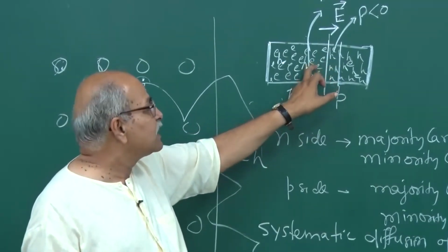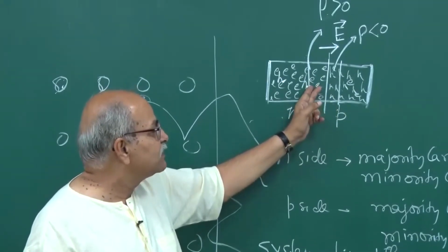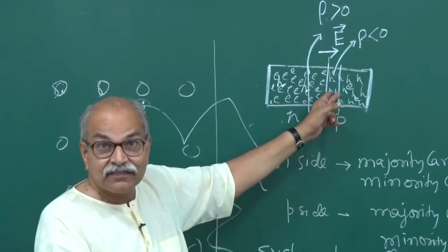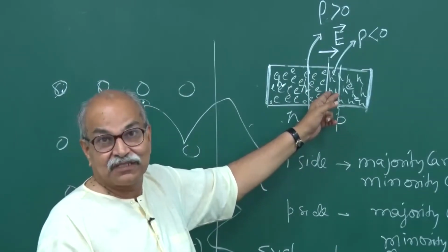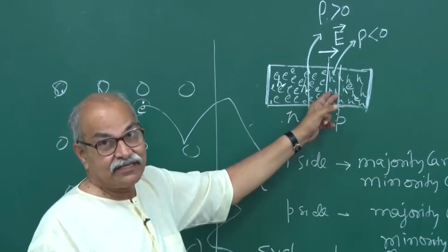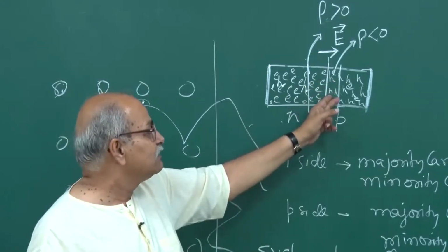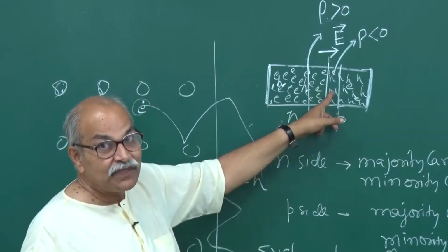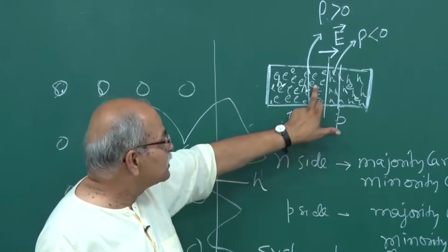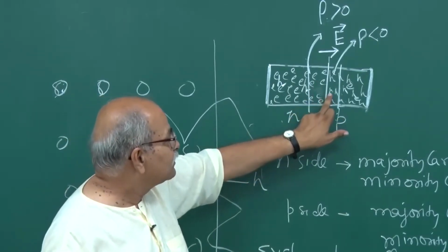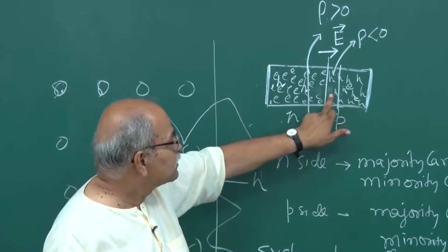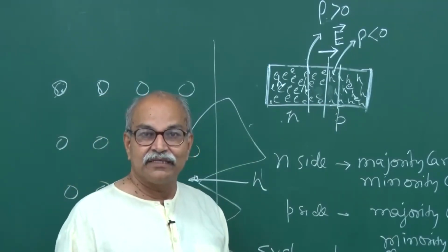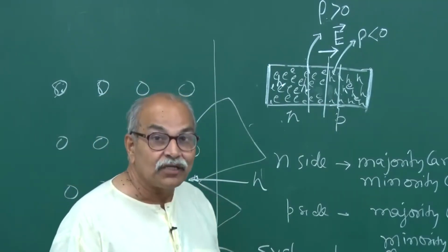So the negative charge carrier electron which has come from left to right finds so many holes there, and therefore one or the other hole will definitely invite it, and it will accept that invitation gladly, and then it will go and fill that hole. Suppose this electron meets this hole, it fills this hole. So now there is no hole and there is no conduction electron, that pair is gone.